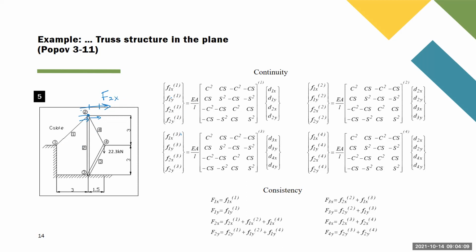That means that, of course, when we don't know something, we have to assume in the positive direction. In this case, these directions are not correct. Probably this will produce tension, this will produce tension, and they will oppose each other. And that will cancel because the total force has to be 0. That's what we're saying here. And with this, we go on. Remember that we have to go in X and also in the Y direction for each one of the 4 joints. That's equilibrium. Remember, discretization means that we only are worried about what happens in the joints.